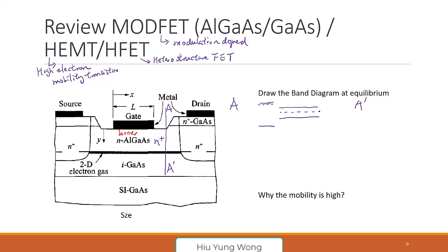How do you draw the band diagram when they are touched together? When it is zero bias, what happened to the Fermi level? Do you still remember when it's zero bias? Constant everywhere. Yeah, this is very important. Once you draw out it is constant, the rest will be easier. Far away, it is still like this, right? Far away from the interface. But then we know that there's a discontinuity. So if you solve the Poisson equation, you will see something like this, right?